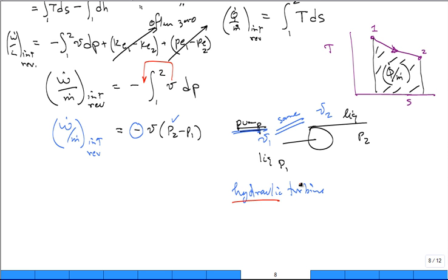You have a lot of liquid water backed up. It's a big lake behind you, right? That you put through a turbine. The turbine doesn't change the volume of the liquid flowing through it. It just drops the pressure. As it drops the pressure, it extracts a lot of energy out. You can use the same thing here. The same equation works.